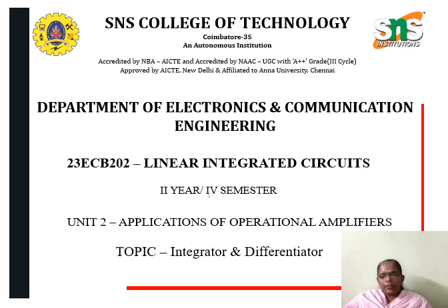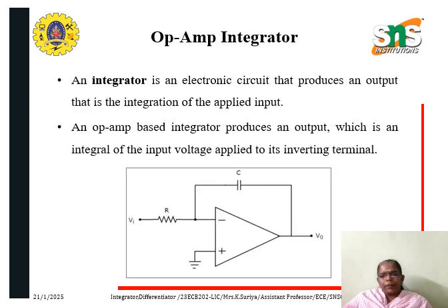In this video, let us see an important application of op-amp, which is integrator and differentiator. In all the two mathematical operations, integration and differentiation, an op-amp can be used to perform these two operations. An integrator is an electronic circuit that produces an output that is the integration of the applied input. An op-amp based integrator produces an output which is an integral of the input voltage applied to its inverting terminal.